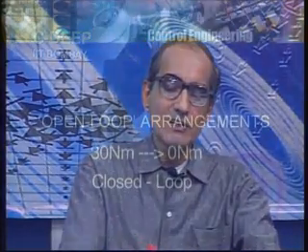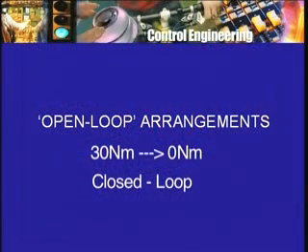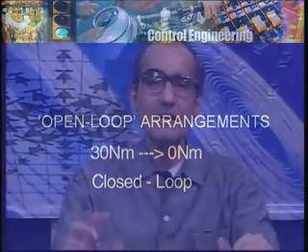And secondly, with the closed loop arrangement, that is the arrangement that we have been talking about, where feedback is used, you have the tacho generator, the reference voltage, the error detector, the amplifier Ka, and all that additional stuff, and all that is the controller now, plus of course the IC engine and the generator which is driven by it and so on. This whole thing is now my controller. The plant is still the same old DC motor driving the grinding wheel or whatever it is.